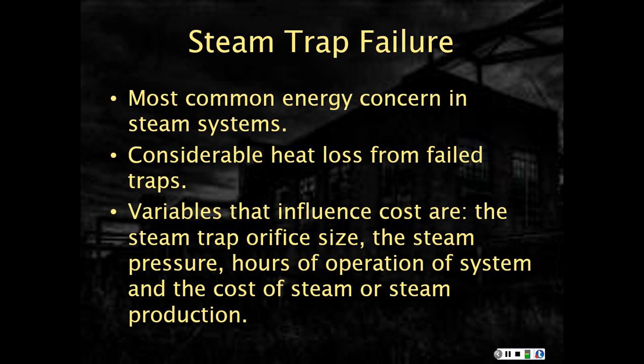Now, the variables that influence cost, in other words, the cost of what this leaky trap is doing to me, is the steam trap orifice size. In other words, how big is the orifice or hole inside the trap, the steam pressure, and if I'm dealing with cost, now I need to know the hours of operation of the system and the cost of steam or steam production.